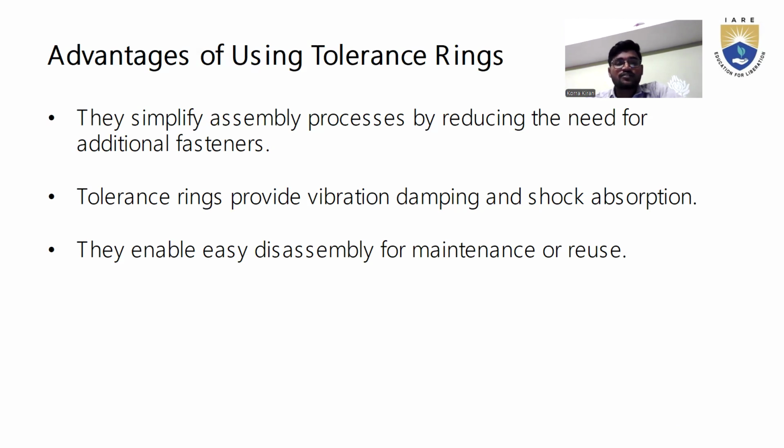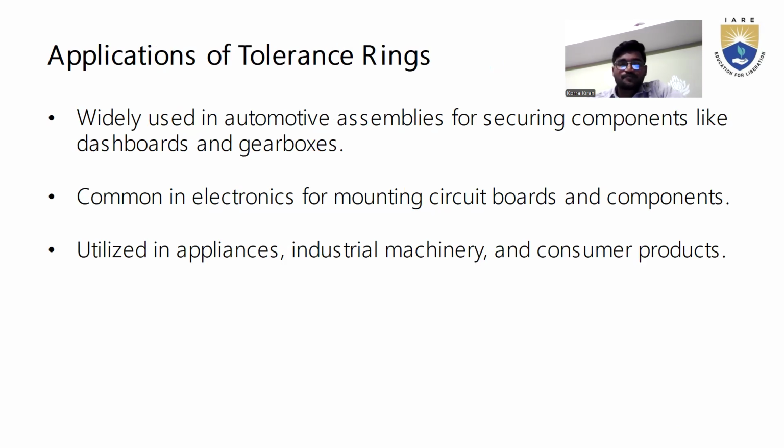Here, one advantage of this tolerance ring is that there is no need for any additional fasteners, and it can provide vibration damping. And other than this, we can easily disassemble it, and we don't need any other force for disassembling the tolerance ring. Now, applications of tolerance rings.